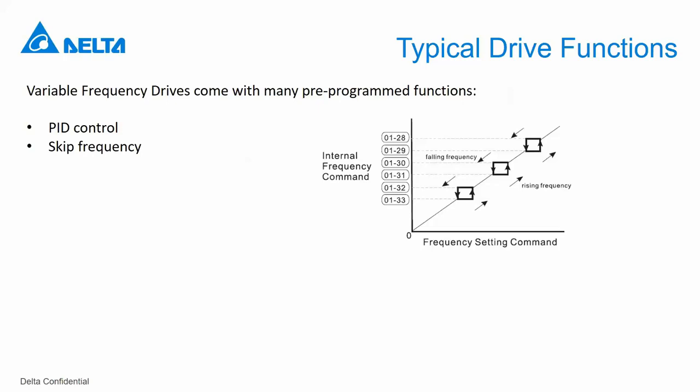So you don't want to give the drive a reverse command and a forward command. You want to do it just with the analog input. So for instance, if you give it minus 10 volts, then it runs reverse. And then when you give it plus 10 volts, then it runs forward or something like that. If I understand your question correctly, that is possible.